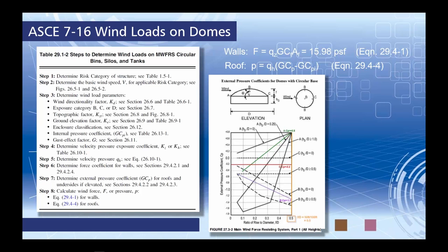So for dome roof loads, we need to first consider the wind direction, of course, and then we have some various points here where our magnitude will vary. We have points A, B, and C. Now, for the external pressure coefficients, the code allows us to interpolate, and all of these interpolations are based on the geometry of our dome. For example, the roof height, the wall height, the diameter, which we'll find the appropriate values here within this figure, and you can see my colored lines where I have interpolated based on our dome today.